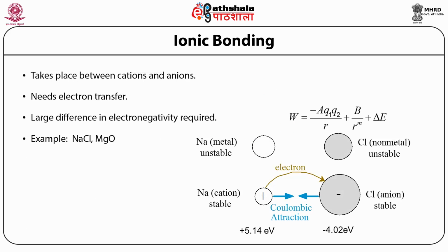Ionic bonding. This bonding occurs due to two oppositely charged elements, for example in NaCl, MgO, ZnO and so on. The electron transfer from one ion takes place to the other ion. The higher the difference between the tendency to accept and give away electrons, described by the difference in electronegativity, the stronger the bond formation. Due to spherical symmetry of atoms and thus the bonding force around the atoms, ionic bonding is not directional in nature. To begin with, ions can be treated as point charges, and when two charges are brought closer to each other,